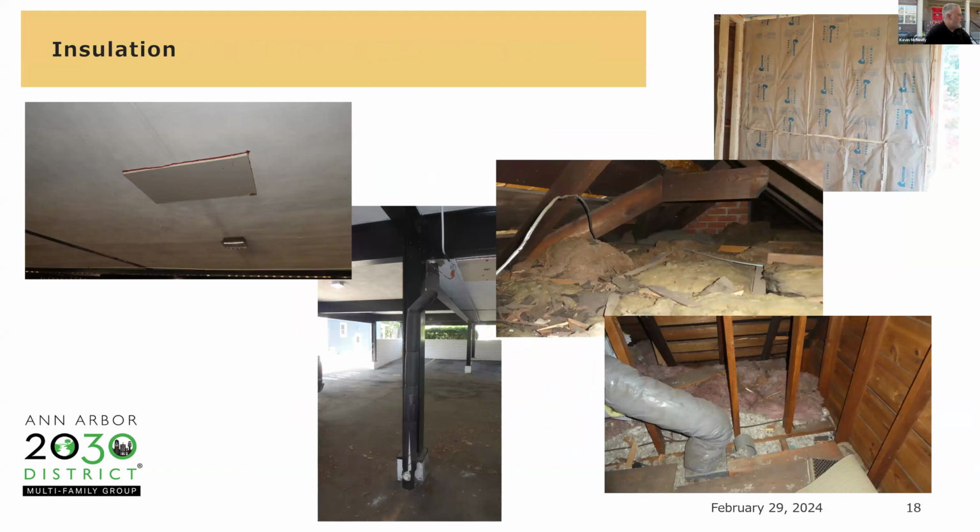And then getting into the insulation. Wherever you have a chance to improve insulation, I would encourage it. The picture's on the right here. If you're redoing a kitchen or a bathroom, I would encourage you to remove the drywall and insulate where you can, and then put the drywall back up. It's a relatively inexpensive thing at the time of construction.